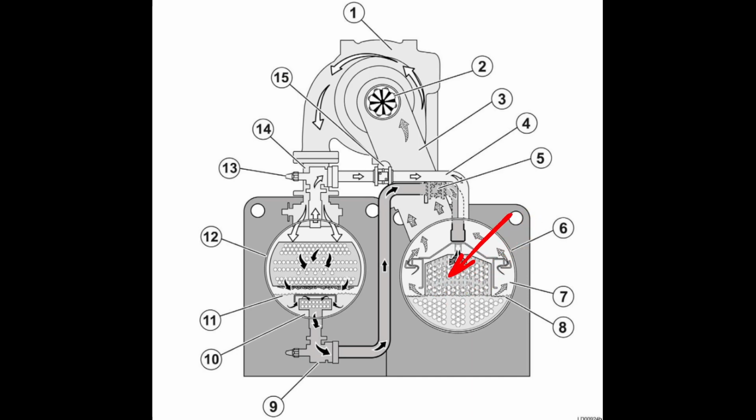And the benefit of a hybrid falling film is that part of the evaporator is a flooded design in its nature. So we spray enough to get a lot of heat transfer on the upper tubes, but then the lower tubes that are fully submerged get maximum heat transfer because the water in the tubes is able to make a lot more surface contact time with liquid refrigerant to cool it down.